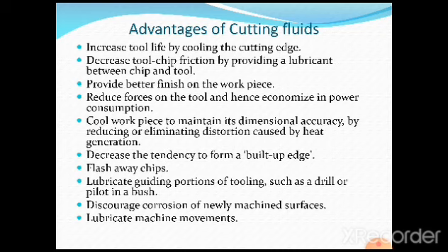Flush away chips. This is one more major advantage. Whenever the cutting action takes place, as we studied while learning about the different types of chips, the metal chips which are being cut during the cutting action have a tendency either to stick to the workpiece or to stick to the cutting edge of the cutting tool. If the cutting fluid is there, it will flush away and make the cutting chips fall down in a tray, especially which you are going to see in your regular lathe machines or CNC machines.